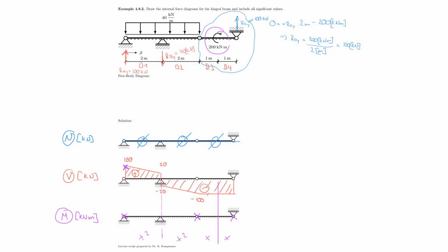So let us draw the slope upwards, upwards, upwards, and then I have to have a slope of 0 there. Actually, it's funny, there's like an immediate kink there because the shear force diagram jumps to 0.